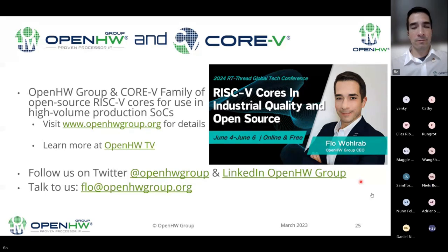Is the core optimized for FPGAs, as a soft core? We do have one core which is optimized for FPGA, but to be honest, this core is currently not under development, so I would not suggest using it. It had a good quality, but the last update was 1.5 years ago. So I would recommend taking one of the latest cores, and even though they are optimized for ASIC or silicon, you can still compile them for FPGA. You may need a few more lookup tables to do so, but it's possible.